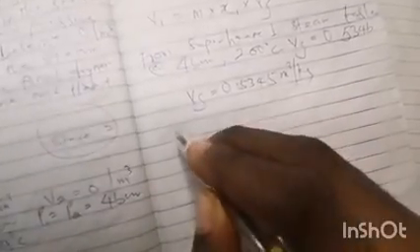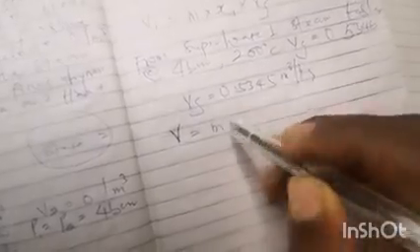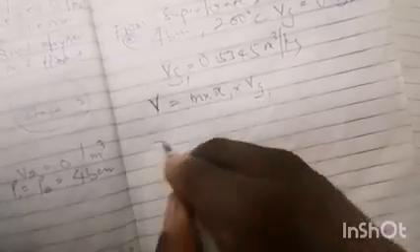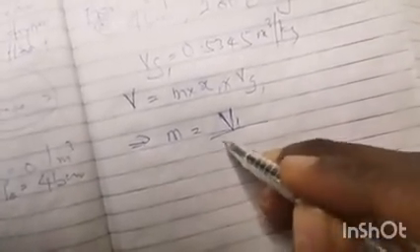So now V1, which is the total volume at state 1, is equal to mass times dryness fraction at state 1 times specific volume at state 1, which is VG, call this VG1. To make mass the subject, mass is equal to the total volume at state 1, V1, all over the dryness fraction at state 1 times the specific volume of the gas.